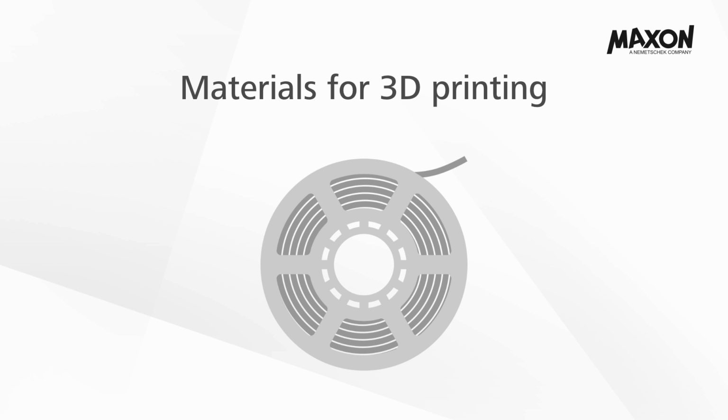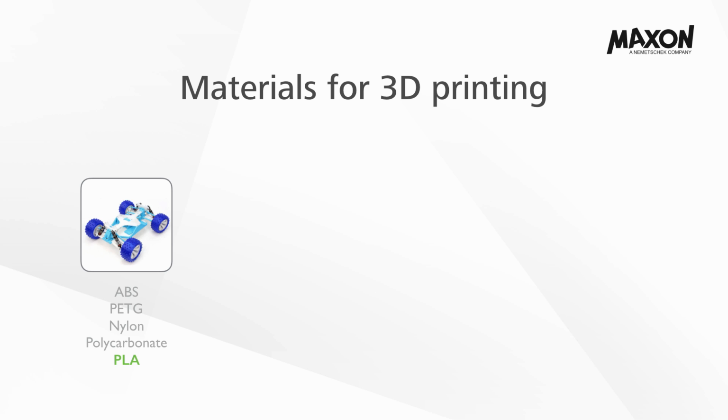I'd like to talk a second about materials. Popular 3D printers today use plastics to create models, the most common being ABS and PLA. ABS derives from the oil industry and is used in most injection molded products such as toys, household items, gadgets, and so on. PLA is a plastic made from plant-based materials and is therefore a better choice from an environmental point of view, but it also prints beautifully and it's very easy to use.